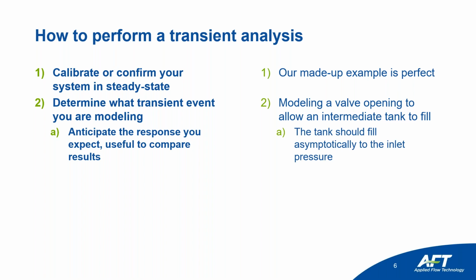it should fill asymptotically to the inlet pressure. So as the tank accumulates more and more mass, it's going to accumulate more and more pressure as well. That's going to decrease the driving force, so we're going to see less and less mass flow going to that tank. So those are the two expectations that we have, and those are the two expectations that we're going to try to confirm within the software, and then it'll do the actual number crunching, so it can give me a specific time to fill it, and not necessarily just the trend that I should be expecting.